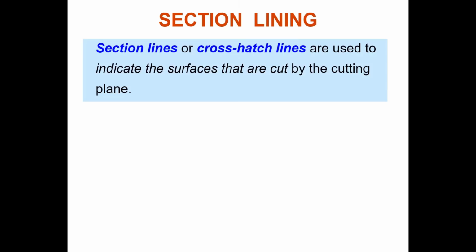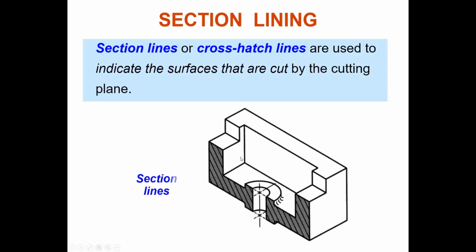Understand, sir. Take note, because this is an online class it's difficult for me to demonstrate. Okay, this is the section line. Section line is 4H. I'm right. 4H. Clear? Do you understand, class? Understand. The lightest one. Because if you make the section line in your front view, for example, using HB, it overlaps with your hidden line, right? Hidden line is HB, center line is HB. So you already have all the hatching lines, and we cannot distinguish which is the center line or hidden line. So the section line is the lightest one, 4H, okay?